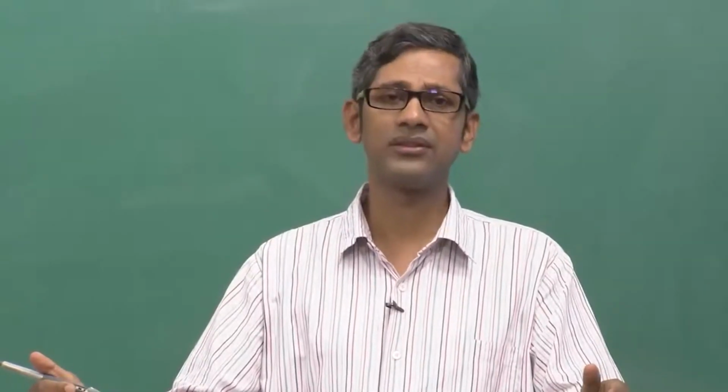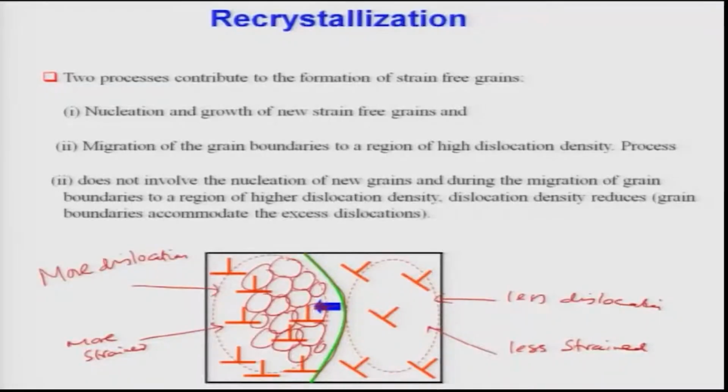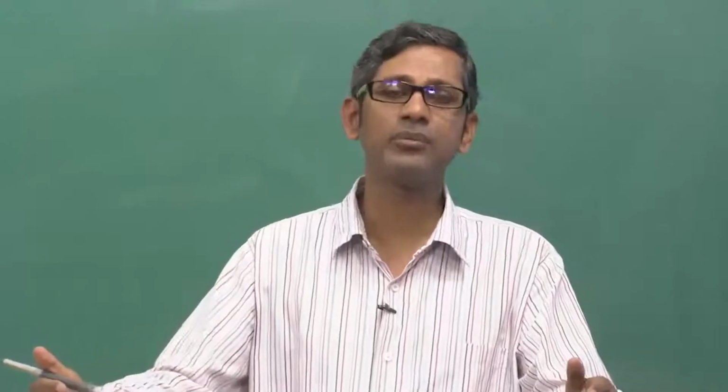Recrystallization means formation of strain free grains in the deformed structure. Now, as I said, there are two important processes which happen in recrystallization. One, obviously, is nucleation and subsequent growth of these grains, but most importantly, the migration of the grain boundaries from a region of highly deformed structure to a relatively low deformed structure happens, and this is the factor which contributes to the nucleation of the grains. One has to understand that the stored energy during cold work is responsible for such processes.